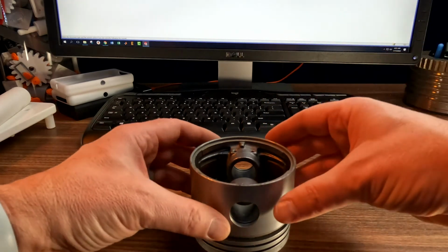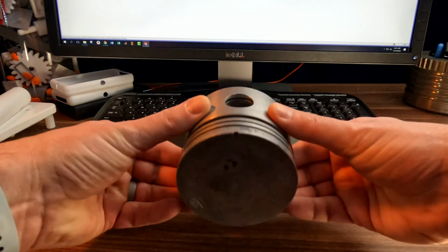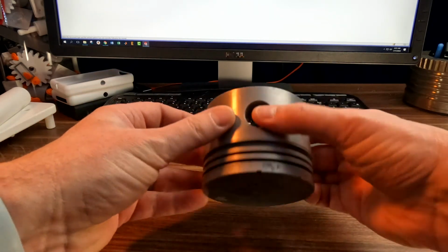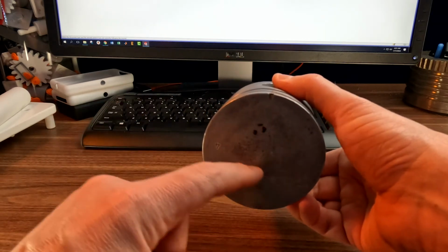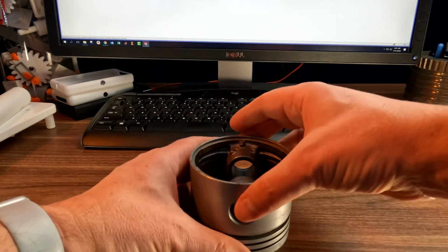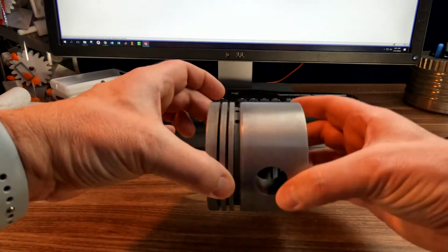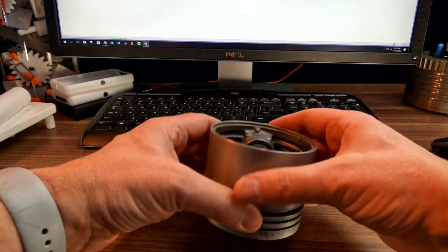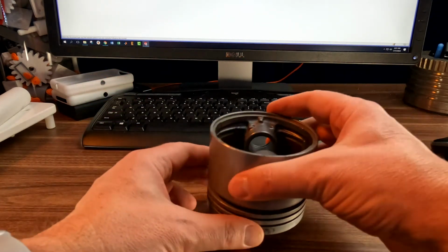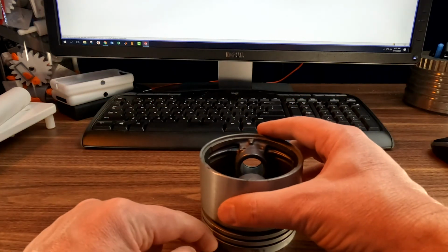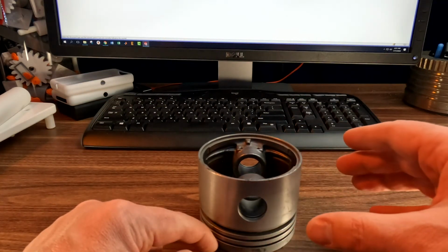I no longer can rotate in the X degree of freedom, because if I do that, then I break the constraint that this face has to be matching on this face. And I can no longer allow rotation about the Y-axis, because again, I need this face to match up to this face. So when I say that I want this face to mate with this face, I have just reduced 3 degrees of freedom.